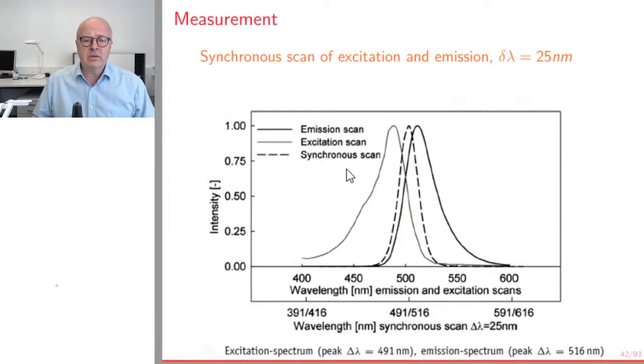tracer. Now, the height of this fluorescence, the intensity, is actually then calibrated. So we prepare several bottles with known concentration in the lab, where we add the tracer to water, dilute it, and we measure this before the experiment at different concentrations. And when we get the bottles in from our experiment, we measure again, and we use this calibration curve so we can translate intensity to concentration of the tracer. This is how it works.